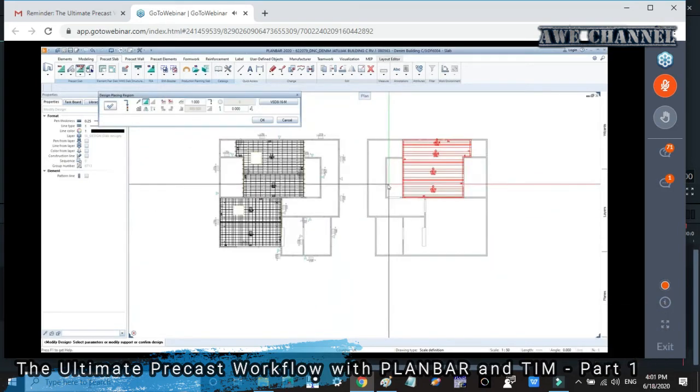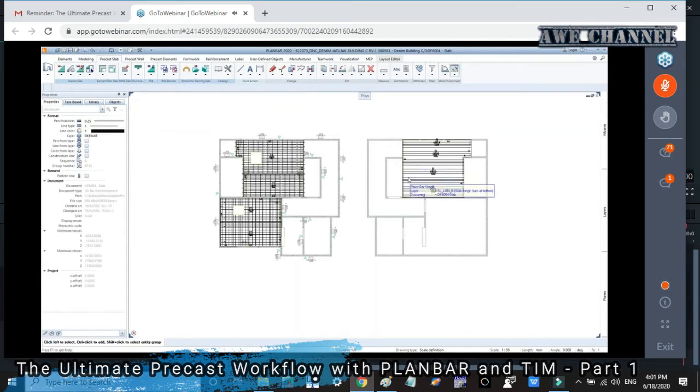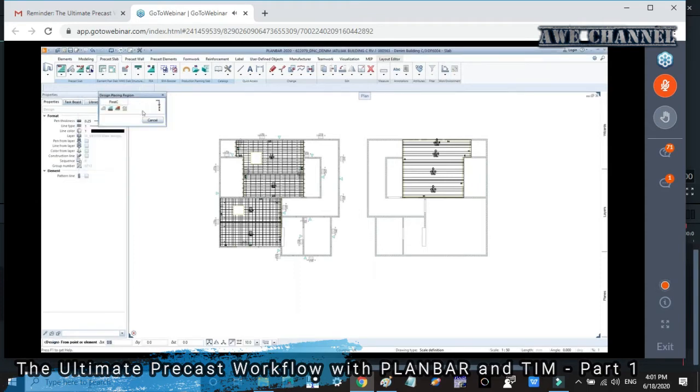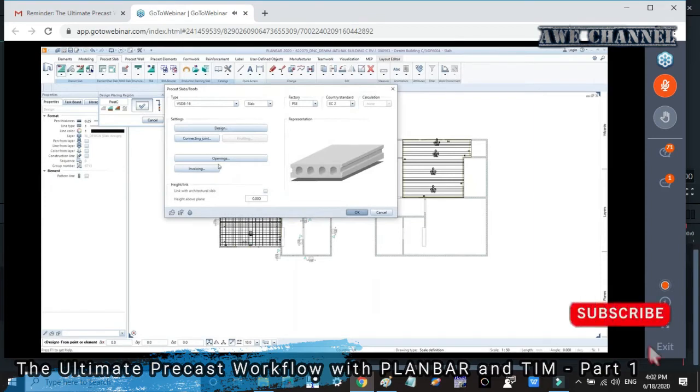And one more thing I want to explain for slab modules. In the slab module, you know we have various types of slab. But mostly people ask me, if you want to move up or move down the level of the slab, how to do it. You just go to height and then define here, okay, I want to move down my slab minus 500. I just put minus 500 here.